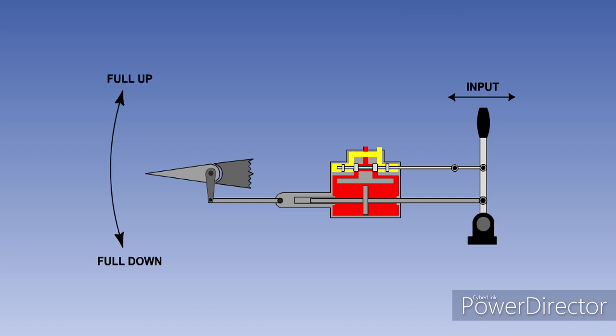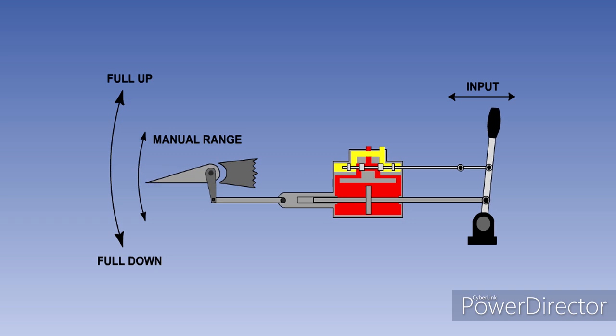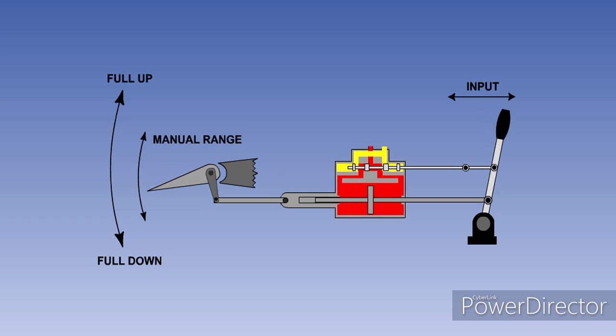We will first look at how the system will operate without hydraulic power. When the pilot makes a control input, he will be attempting to move the hydraulic jack ram. Because of the hydraulic lock, the entire actuator will move, and with it the flying control. However, because of the mechanical advantage gained, the control surface movement will be small compared to the pilot's input. There will normally be sufficient movement available for the pilot to maintain control of the aircraft in the event of a hydraulic system failure.